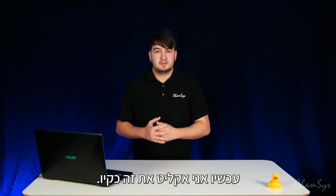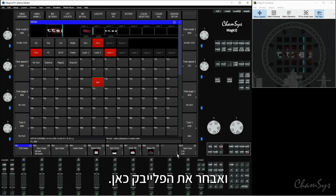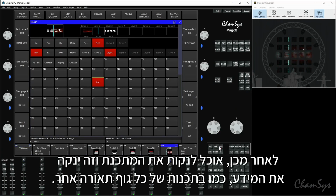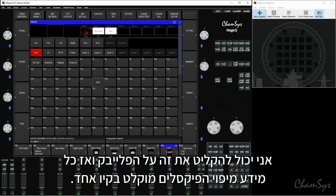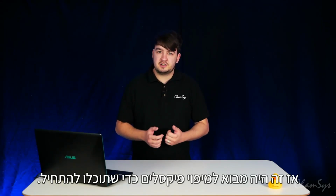What I'm going to do now is record that as a cue. So if I press record, just like anything else, and select a playback here, I can then clear the programmer and it'll clear all of that information just like programming with any other fixtures, and I can record that on that playback, and it's recorded all of that pixel mapping information into a single cue. So that's an introduction into pixel mapping to get you started.